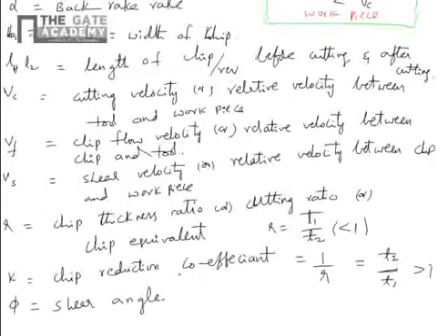Another assumption is that the material is incompressible, and the volume before cutting and after cutting remains constant. Whatever volume reduction takes place in the length direction has to increase either the thickness or width direction, but as we assumed the width is constant because there is negligible change in width, so length and thickness have to vary.